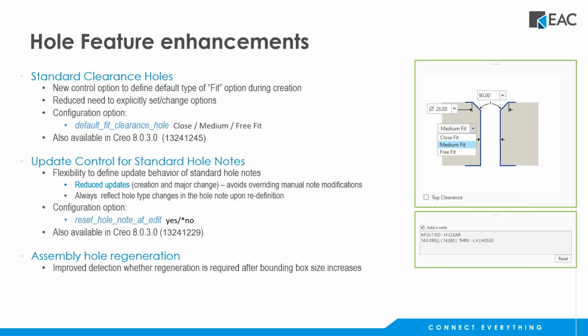All right, moving forward to more of the modeling enhancements. There's been some enhancements around the hole feature. So we now have a configuration option to choose the clearance for our holes. So we can choose a close, medium, or free fit according to the ISO standard for our standard holes.